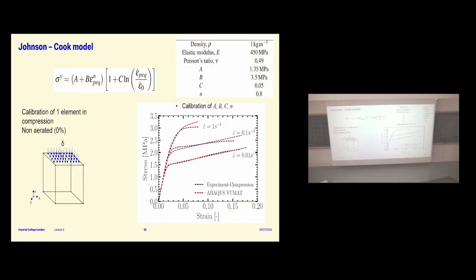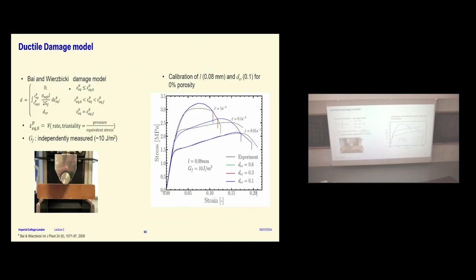I've shown you this on Saturday. These are the stress-strain curves in compression only, and we fitted this phenomenological model for elastoviscoplastic materials. So you get an elastic response, and then plasticity, which is a function of rate. You can calibrate the constants in that equation with the data that you have for different strain rates. What we also wanted to do was to model the softening. You see, these are the curves that we get, stress-strain curves after the peak.